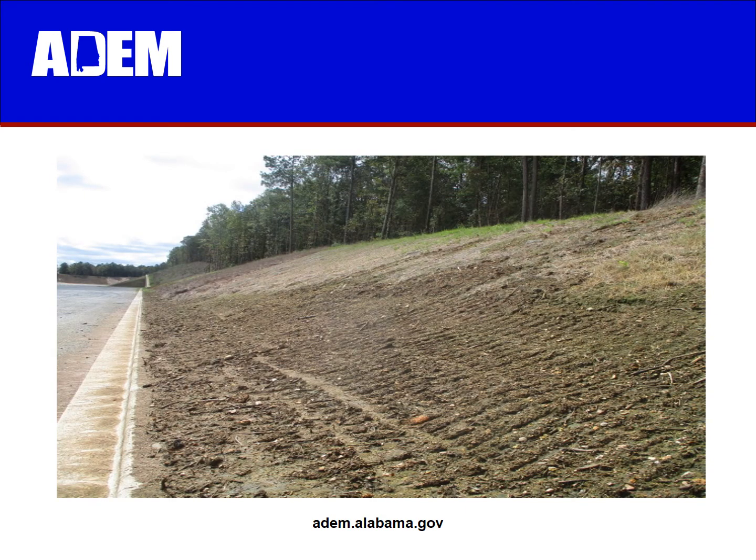Once the final grade is achieved, a final trip over the slopes with equipment should be done up and down the slope so the heavy equipment tracks are on the contour. This slows velocity down the slope and reduces erosion.